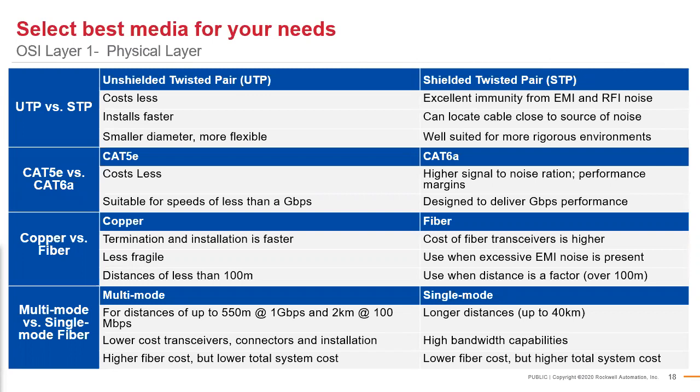Yeah, the rule of thumb these days is single mode fiber is actually less expensive than multimode. Fractionally, to tell you the truth, the cable doesn't cost a whole lot of money. It's the termination, it's putting everything together. But the single mode is always going to require you to use an SFP that is utilizing a laser, which is going to be more expensive than an LED.